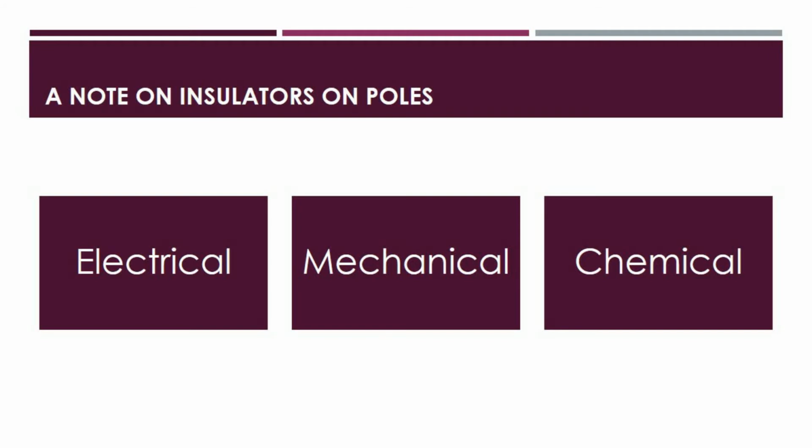Mechanical pressure on suspension and line post insulators is caused by a combination of tensile, torsional, cantilever, vibrational, and compressional forces caused by conductor vibration and galloping. High-density snow or ice accumulation and rapid ice shedding would also be part of the mechanical pressure. Now, insulators with line posts, struts, and pins are unusual in that they may be subjected to a combination of cantilever, transverse, as well as tensile forces at the same time. And damage caused by impact or contact is also possible.